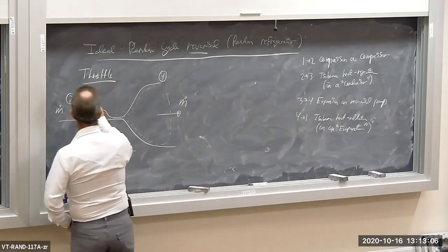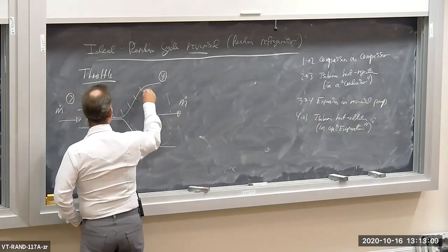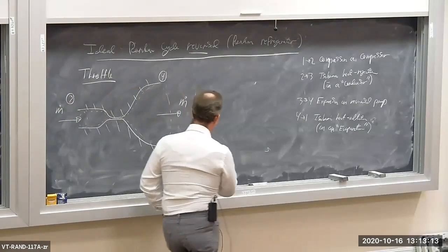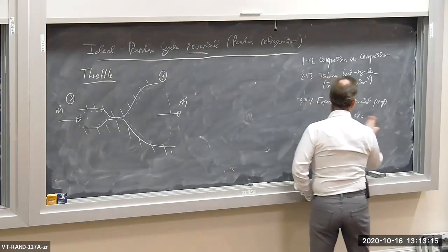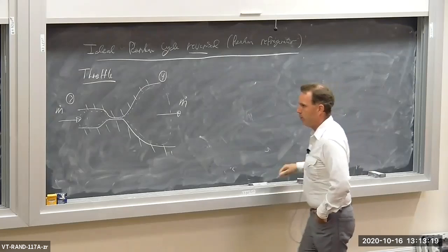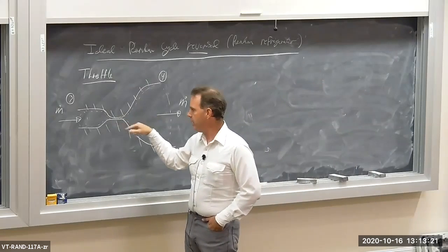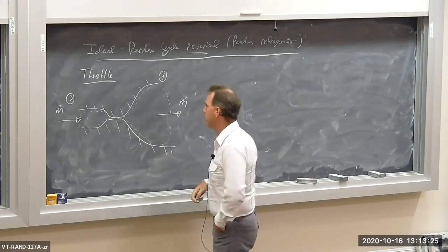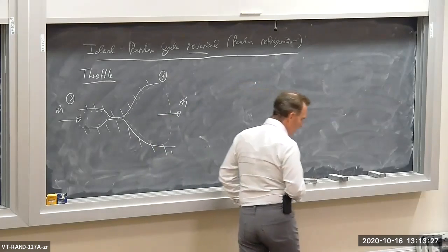Let's say it's insulated. If I apply the energy balance to this thing, it's an open system, single inlet, single outlet. You see any wires in here, any turbines, any boundary work going on? Nope, there's no work going on, no heat transfer.